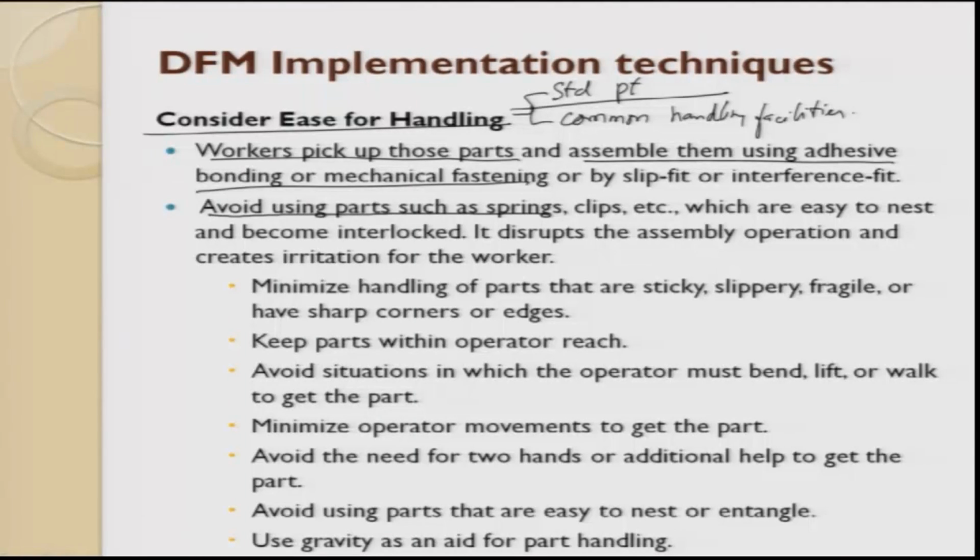Avoid using parts such as springs, clips, etc. Today, whatever function a spring does, the spacer also tries to do the same, and you can have clips which do the same, which are easy to nest and become interlocking. So, these things should be avoided. Minimize handling of parts that are sticky, slippery, fragile and have sharp edges. Keep parts within the operator's reach.